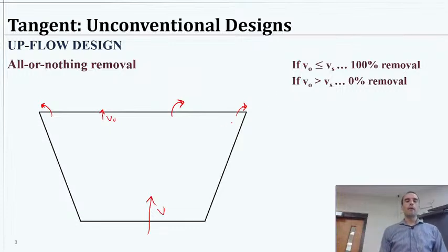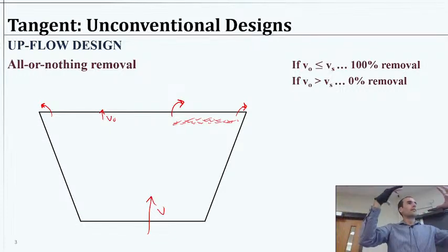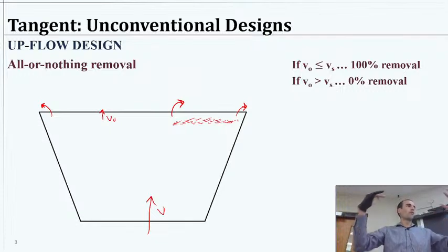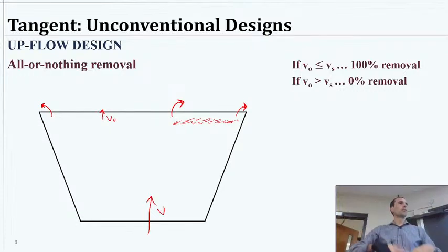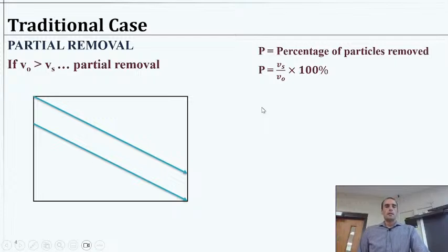And then what you would have is sort of a blanket layer of these particles starting to come together right here where they were meeting, not quite going over. And then they'll gather into larger particles and slowly start settling out. It'll almost form a blanket, and then it'll sort of sweep through the rest of the water, and that can then be a benefit. So there are some interesting things in practice like that. They're not super common, but I just wanted to say those.